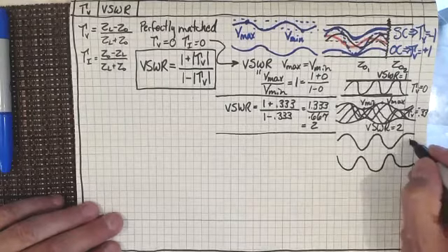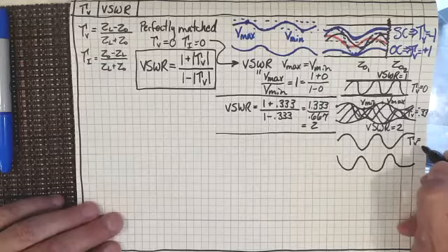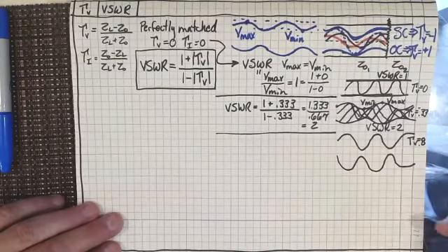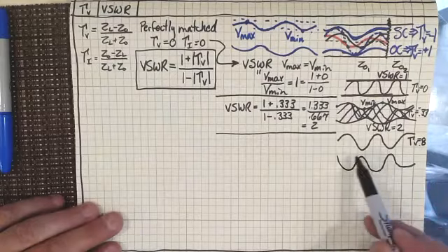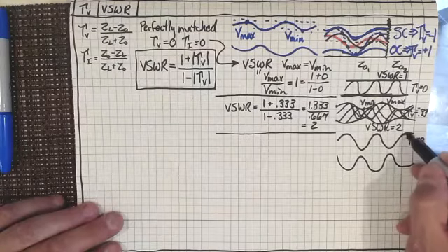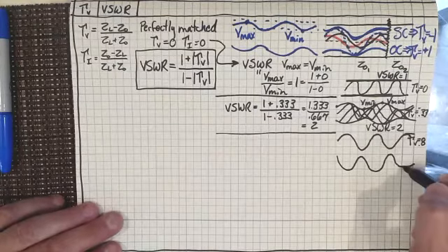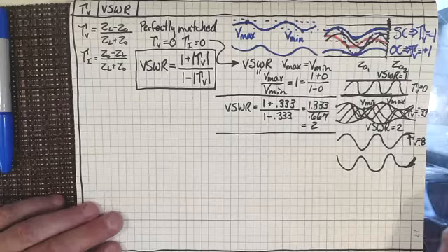This would be a voltage reflection of 0.8, right? Voltage reflection, and this is what my envelope is going to look like. Well, it would come down in here, but I can't really do that because I've now written the number there.